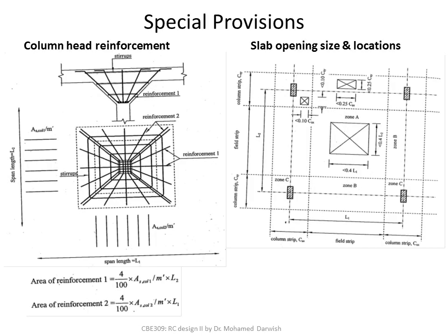And this total moment is distributed on different locations. But there is a little bit of fine tuning here. You need to understand that there is an additional reinforcement for the column head, to distribute the stresses properly within the column head, as you could see here. And there is an additional reinforcement in case of having any openings within the flat slab.